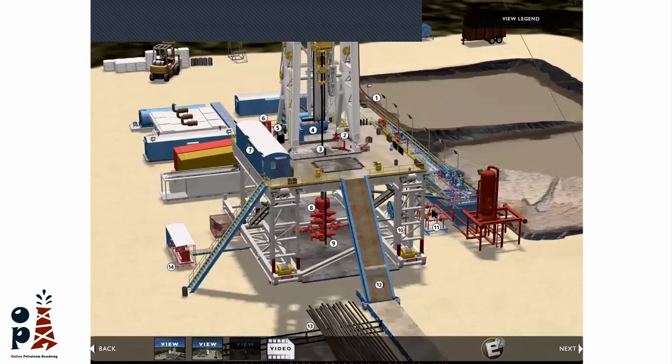Okay, so this is a choke manifold through a mud gas separator. Then this is our tanks. Start with the mud, the sand trap and shale shaker, then the desander, desilter, mud cleaner, then mud gas separator, mud degasser, and then our tanks. And here you can see the mixing area.